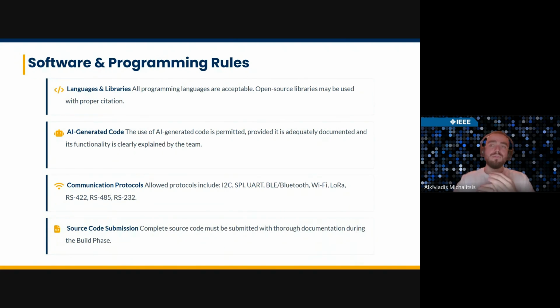Regarding the communication between the different interfaces, sensors, boards, and all kinds of components, we are allowing different communication protocols. The basics that we mention here are I2C, SPI, UART, BLE Bluetooth, Wi-Fi, LoRa, RS422, RS485, and RS232, which I think would be a little redundant based on the voltage that you will work with.